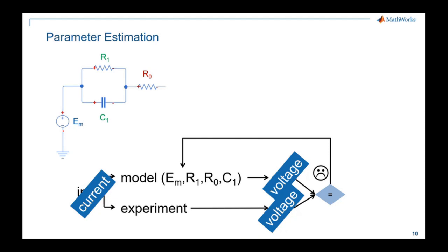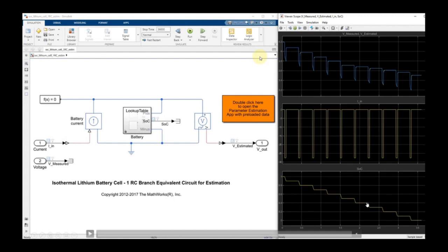Then, once the difference is not accurate enough, we can always look back and tune the parameters, and once everything is fine, we can save the computed parameters. So there are two ways to get out of this loop: either the accuracy is good enough and then we can leave, or you have done a given number of iterations, for example 10, and after 10 iterations you say, okay, that will be enough for my model, I can live with the values that have been computed. And that's what I'm going to show you right now. Here I made a video because it takes a bit of time to do this parameter estimation.